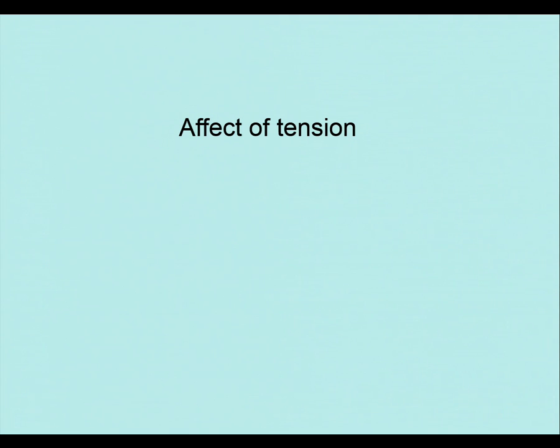To ensure your pipe can be reeled, that's to do with straightening it again, it needs a D over T ratio less than 20, although it's roughly about 19, otherwise it buckles. But if you're going for laying it by J-lay, what's the water depth?